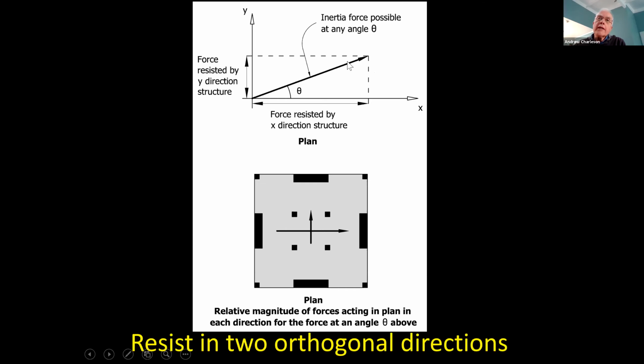And so your job as an architect for every building you design is to make sure that you've got strength in the x direction, these 2 walls, plus strength in the y direction, these 2 walls. And these other columns, you'll need lots of other columns and beams probably, they will resist your gravity loads. They will take the weight of your floor slabs and all the live loads in your buildings. But your earthquake loads can be resisted by these special elements that you will design.